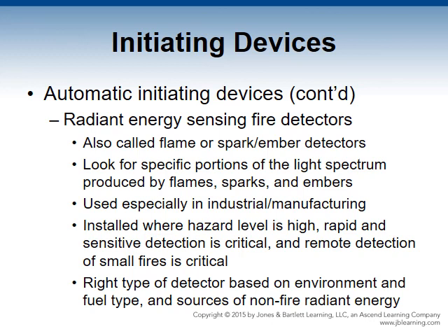Radiant energy sensing fire detectors, also known as flame and spark ember detectors, look for specific portions of the visible and invisible light spectrum produced by flames, sparks, and embers. They are not dependent on smoke or heat plumes.